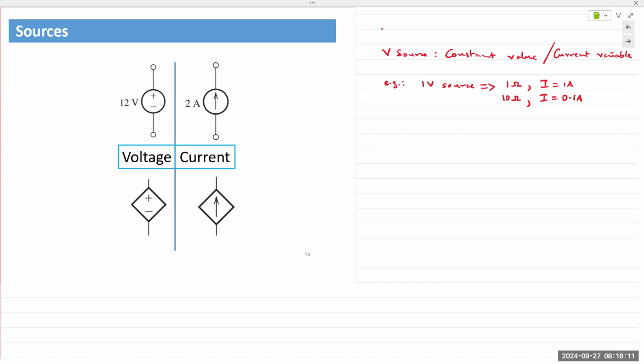So if you have noticed, when you use the DC power supplies in the labs, anywhere in this building or anywhere else for that matter, it'll have a small tiny notation saying CV. And that stands for constant voltage. So the power supply is running in constant voltage mode. And because it adjusts the current depending on the requirements of the load, we have to set a current limit. Sounds familiar, right?